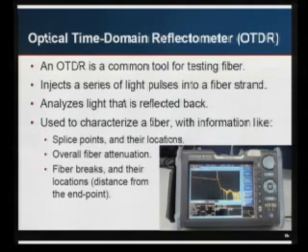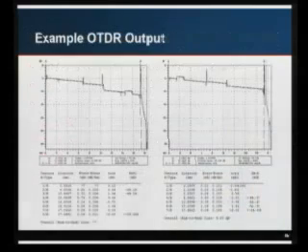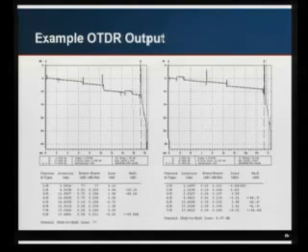And here's a Wikipedia example of an OTDR. Here's an example output of an OTDR from some fiber that I have. You see the major splice points. You see where the signal changes. Basically what it's looking for is events. So it says 2.3 kilometers out there was this event, 6.8 kilometers. It's identifying where all the splice points are because it sees the increase in reflection and the increase in loss, and it can tell you where there's a really dirty splice. Like in here you see there's a splice where there's like a 1 dB loss, which is much higher than you would want compared to a splice which is 0.06 dB loss, which is a well-engineered splice.